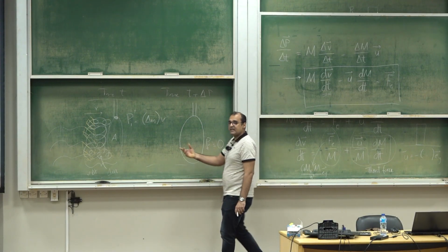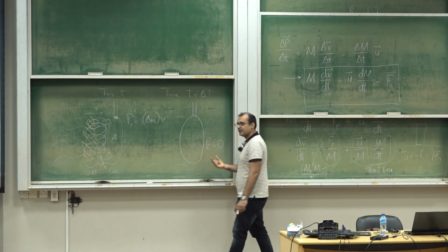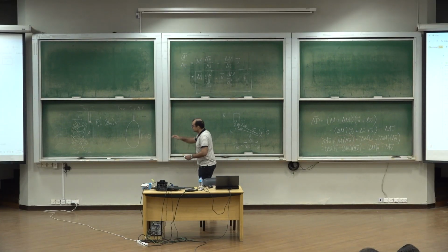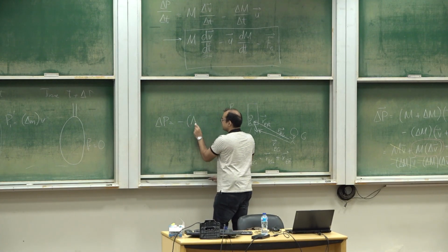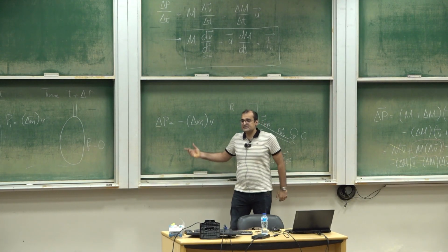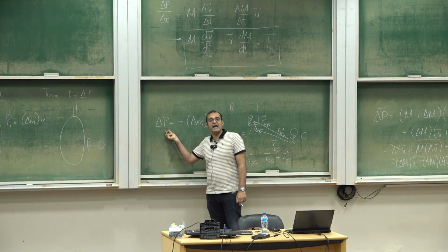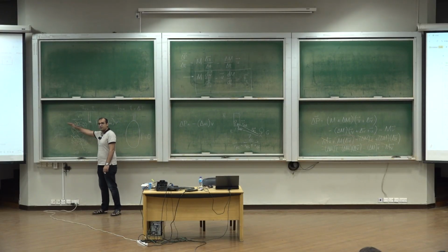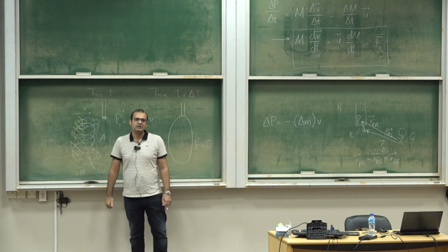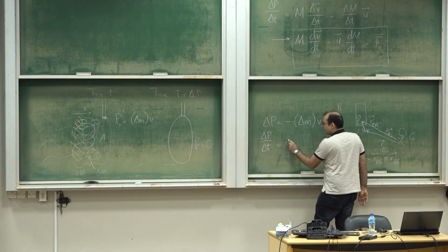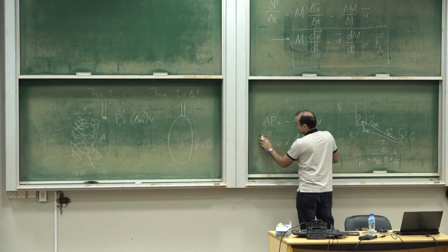Okay, so the momentum of the air molecules at time t is equal to that, the momentum of the air molecules at later time equals that. Okay, how do I calculate the change in the momentum? Final minus initial, so the change in the momentum equals minus delta m times v. ये माइनस क्यों आया? Because this is the change in the momentum of the air molecules. इसको divided by delta t करोगे तो क्या आएगा आपके पास? The force exerted by the disk on the air molecules. And of course the force exerted by the disk on the air molecules must point to the left. इसलिए तो रुके हैं वो एयर मॉलिक्यूल्स, आपके इनिशियली उस तरफ जा रहे थे, वो फोर्स इस तरफ लगेगी तो वो रुकेंगे ना. Okay, so delta p over delta t equals, ignoring the sign, we just know that direction, वो है v dm by dt, if dp by dt इसको बता.